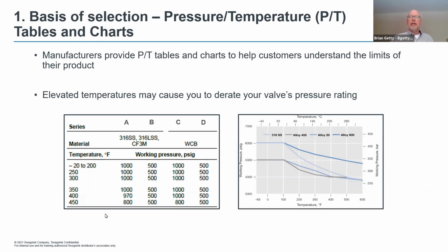All right, in this chart, this particular valve has a capacity of 6,000 psi. Here we have indicated this is your working pressure, marked down here, working pressure, 6,000 psi, and I'm dealing again with 316 stainless steel. This is the line for the 316 stainless steel. So we start at 6,000 psi at -65 to 100 degrees Fahrenheit. I'm also dealing in Fahrenheit here.